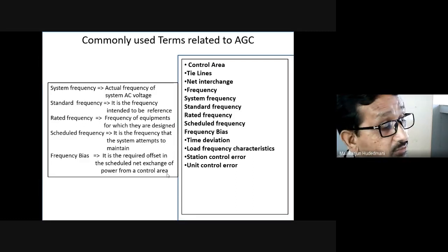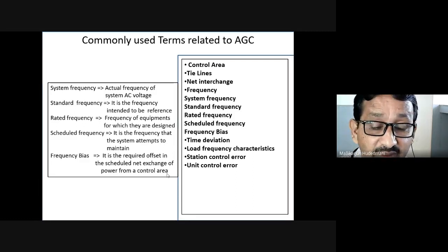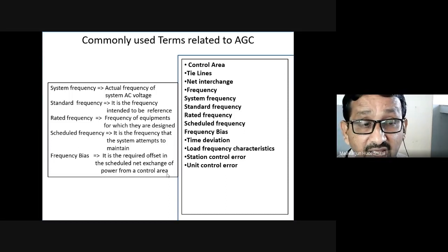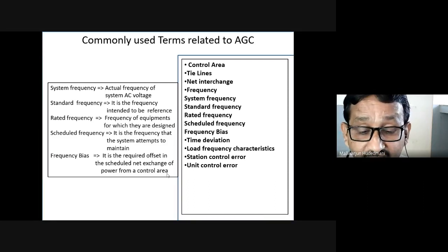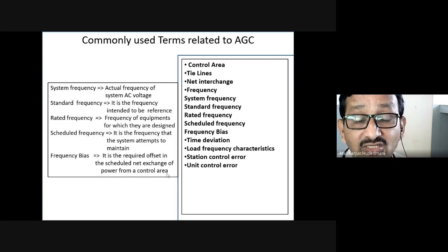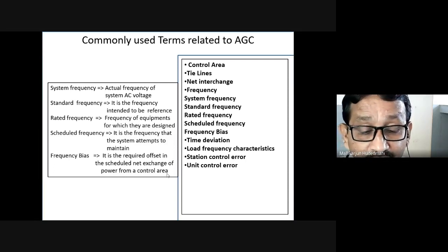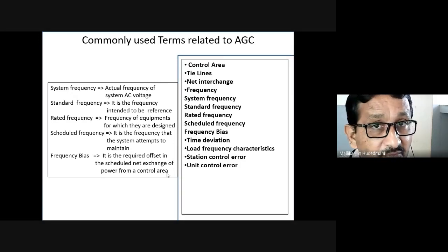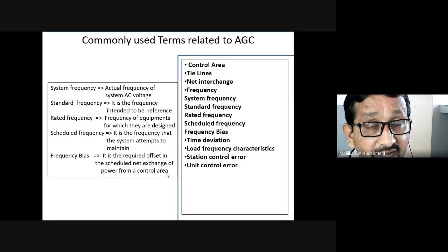That is the stimulus we are going to get from this frequency bias. Frequency bias is the net set point change at the generator for a drop of frequency due to a rise of load on the station. It means we have a very particular relationship of active power with frequency in the power system, the dependency of frequency and active power.